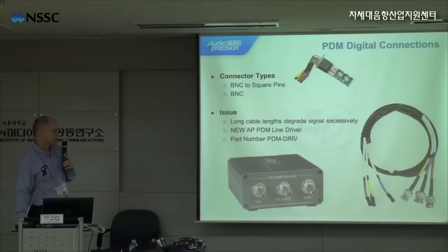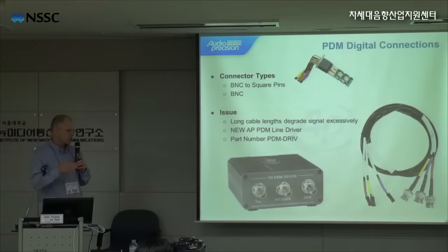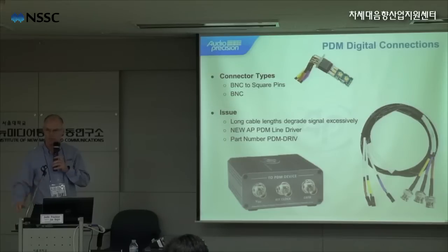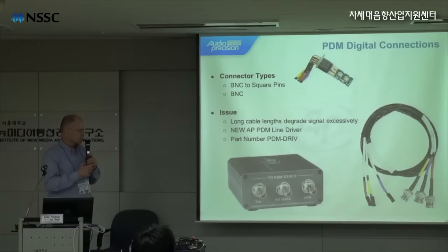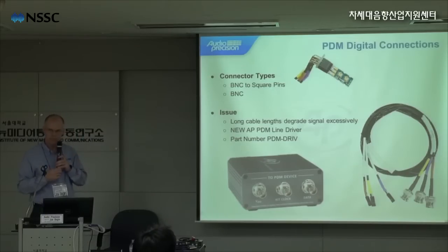And what this does is you can put this between the analyzer and a long cable, and it allows you to drive a much longer length. So for example, if you're testing these microphones in an anechoic chamber, you're going to want to have the analyzer with its fan outside the chamber, and you can use this line driver to use a longer cable to put the driver inside the chamber and not degrade your signal.